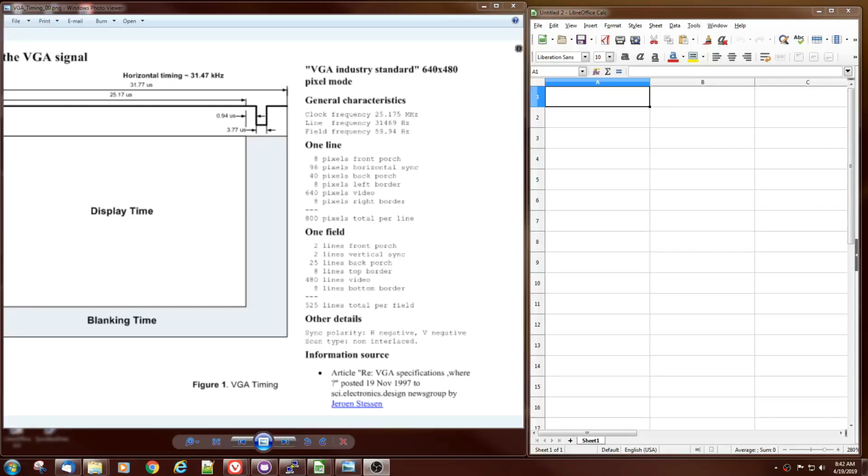Grant's original design for the SuperBoard upped the video to 64 columns by 32 rows. In a previous video, we got the display to run on a VGA instead of the composite, which is what it was originally designed for. The limitation of this was that it produced a small picture within the larger screen. Let's take a look at what it'll take to stretch the video on the UK101 display.